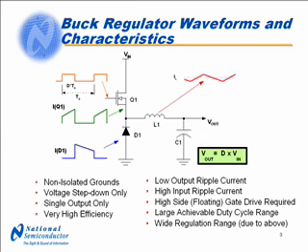Each cycle, the inductor current ramps up while Q1 is turned on and then ramps down while the diode is conducting. The MOSFET and diode currents sum to form the inductor current. The current waveforms are shown on the slide.